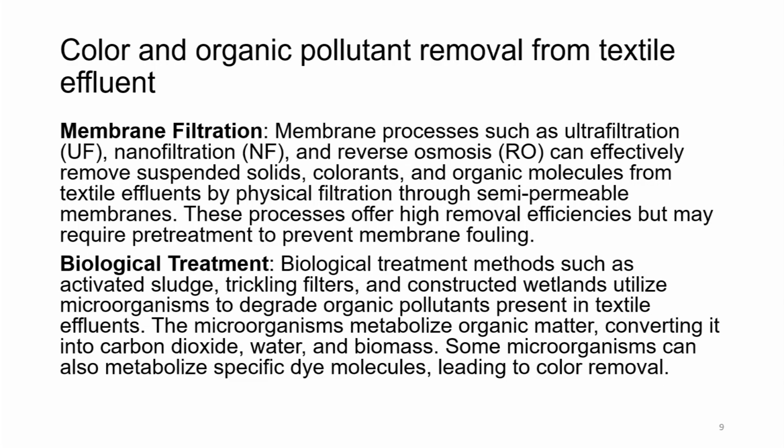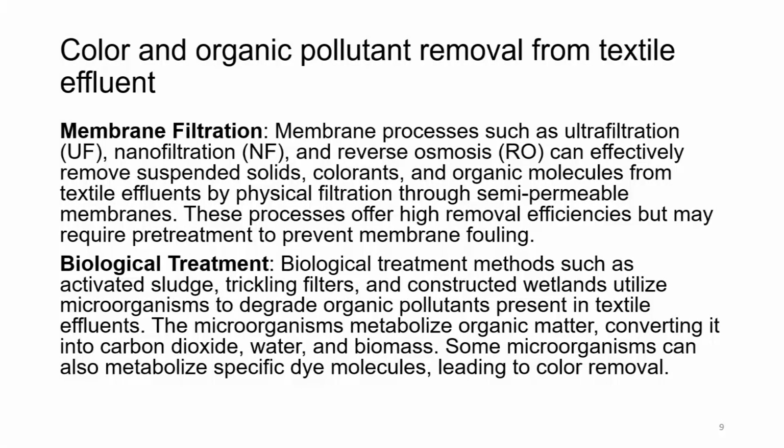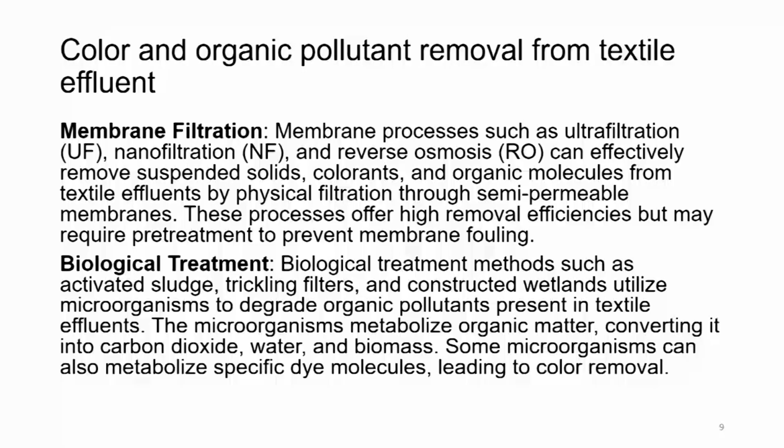What is a semi-permeable membrane? A membrane which can allow certain molecular weight size passage through the membrane pores and not bigger sizes. So, it is semi-permeable, it permeates only smaller molecules and not larger molecules. These processes offer high removal efficiency, but may require pre-treatment to prevent membrane fouling.